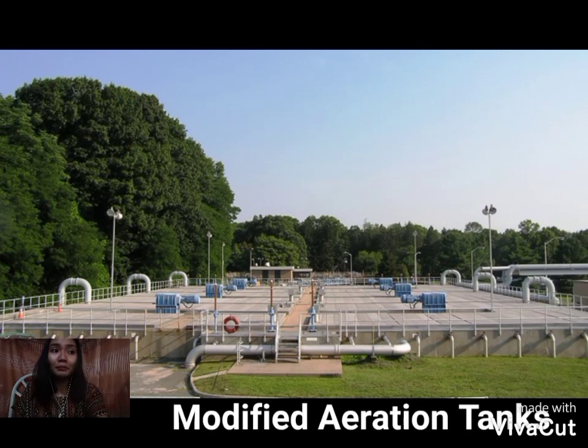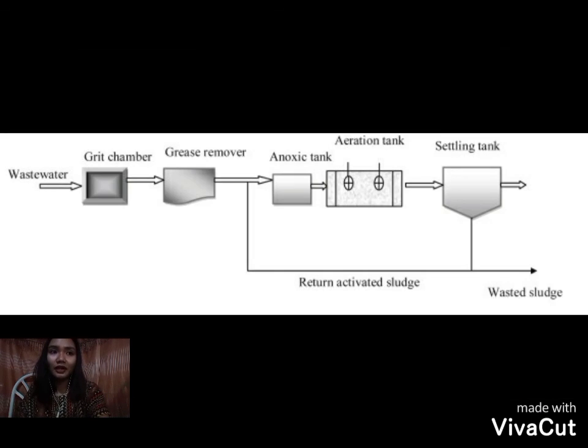Next, we have the modified aeration. It is similar to conventional plug flow, except that shorter aeration times and higher food to microorganism ratios are used. The BOD removal efficiency is lower than other activated sludge processes.